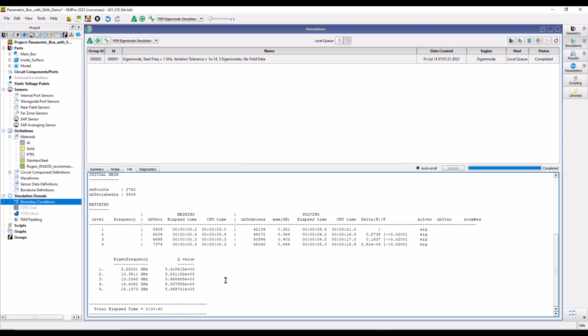Well, if you remember, in your RF microwave circuit, you will have a certain amount of radiation from your circuit. It could be very small, but it doesn't matter because it is impossible to contain 100% of the electric field within the dielectric. You will have various discontinuities in your design which might create a small bit of radiation. And since you have a cavity resonance happening at the same frequency, that resonance will be picked up, and then that can be added in a destructive or a constructive manner with the rest of the energy propagating through your structure. And that's precisely what is happening in our case.